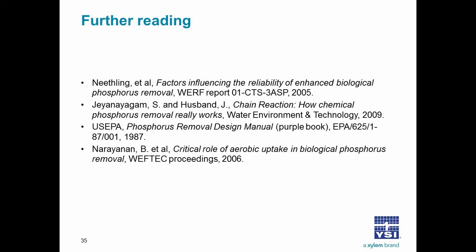There are a lot of choices, and I can relate my original experience with this when I was an intern at the City of Toledo Bayview Wastewater Plant. They added the chemical to the grit tanks, they had aerated grit upstream from the primary clarifiers, and I thought that was the only way it was done, and it seemed to make the most sense. Because the chemical takes some of the additional BOD out of the water, it seems like you would have fewer competing side reactions.